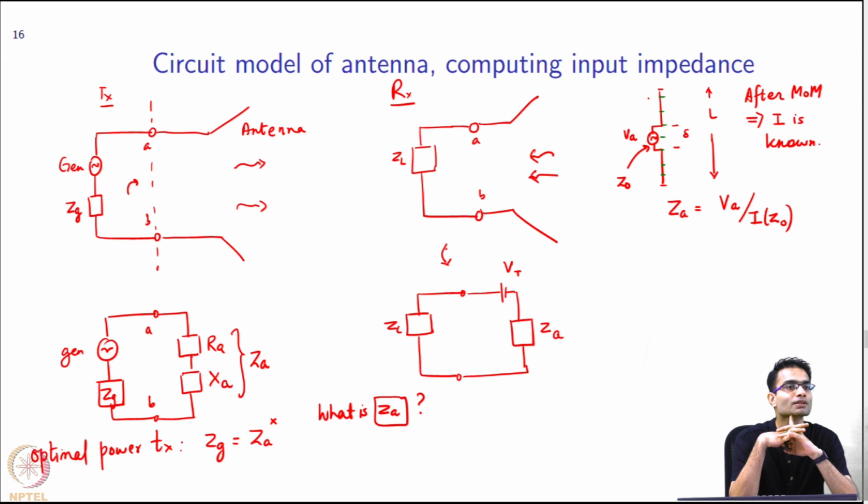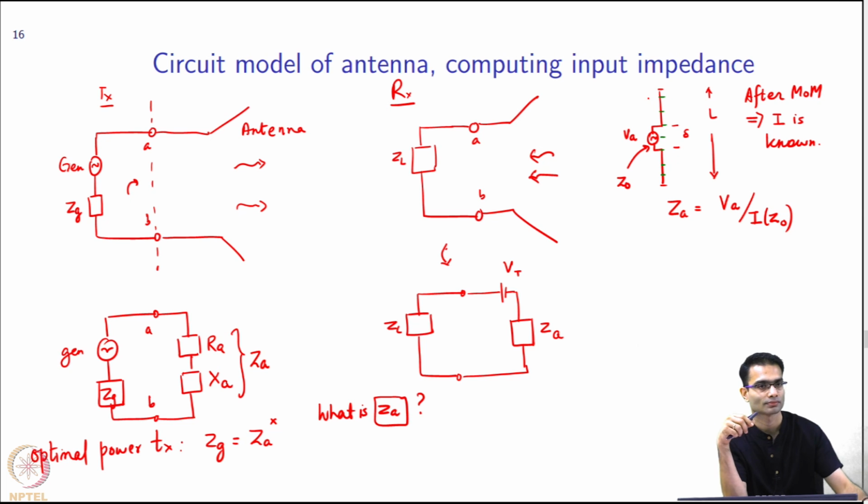You cannot match the free space impedance. You can't match that. I mean, you have your circuit impedance as, let's say, 50 ohms or 75 ohms, and then you have to match it over there. You can't match free space. Not all the radiation is going to go into free space. You live with that. Okay, so the procedure is clear. How do I calculate the input impedance?